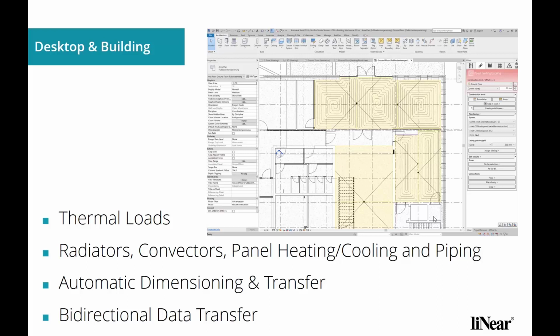After you complete your building detection, you can easily calculate the thermal loads of this building. All load calculations will be based on valid standards such as ASHRAE and European norms. The program will direct you and ask for missing parameters for heat loss and cooling load calculations. When you finish inputting parameters, results will be displayed.